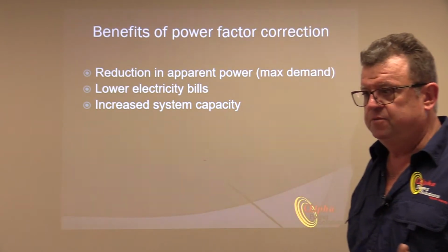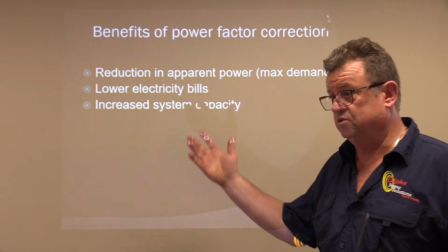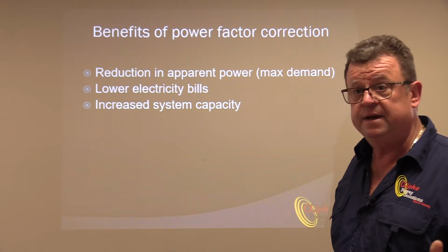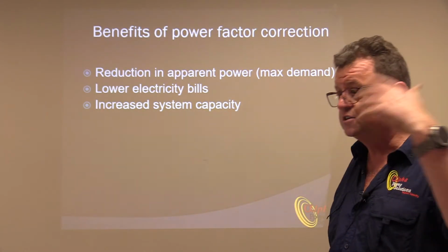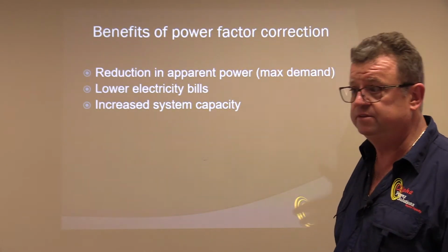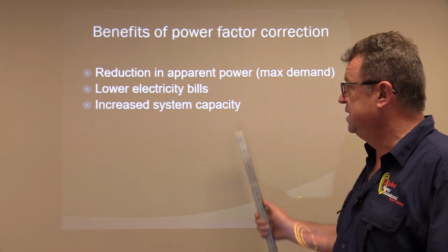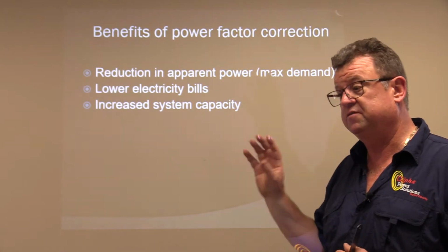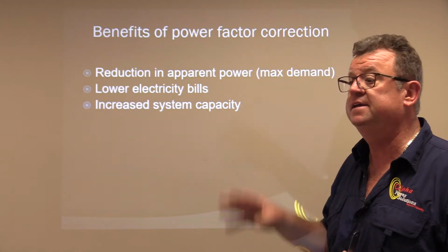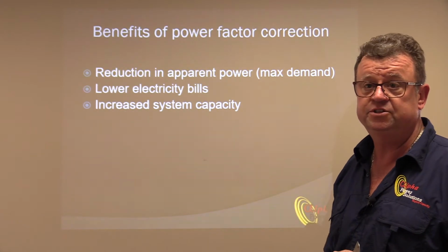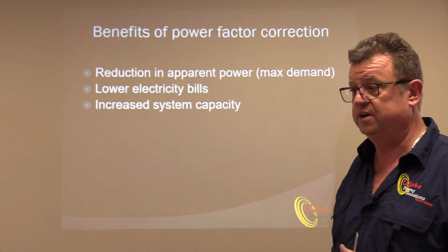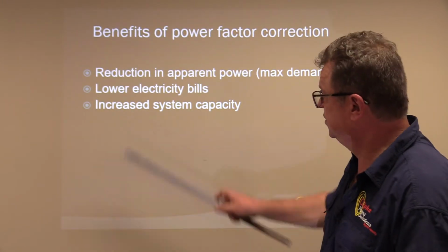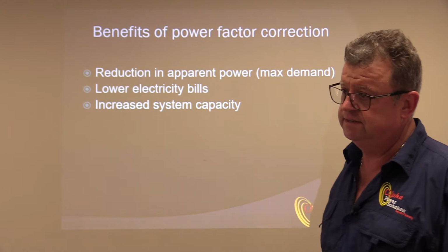the investment of an upgrade is ridiculous, because it's your MV supply that needs to change, your transformer needs to change, your distribution panel needs to change, because the bus bars will be underrated, the main breaker will be underrated, so all that stuff. So then the savings are basically based on the profit that the customer is going to make by being able to install that additional machine without an expensive upgrade of the electrical supply. No, that's interesting. So we call that capacity, freeing up capacity.